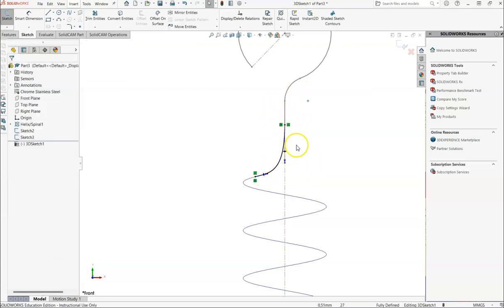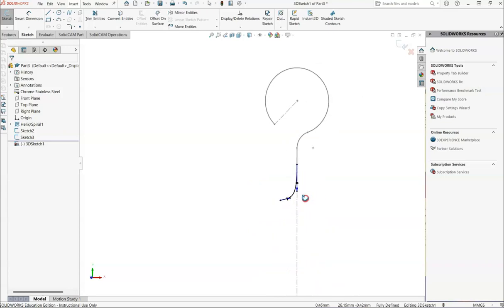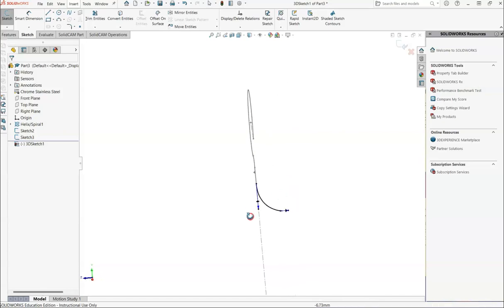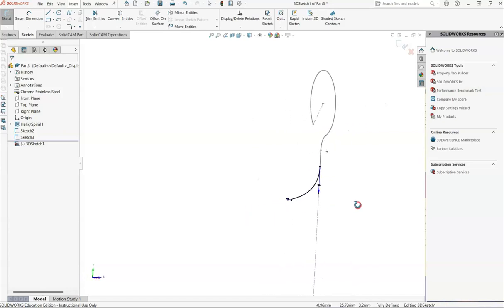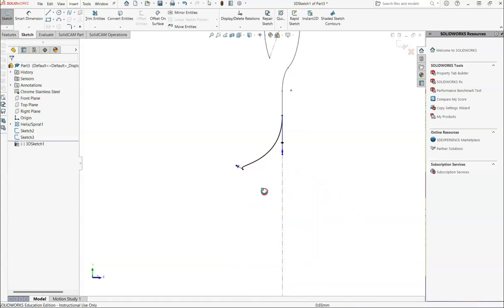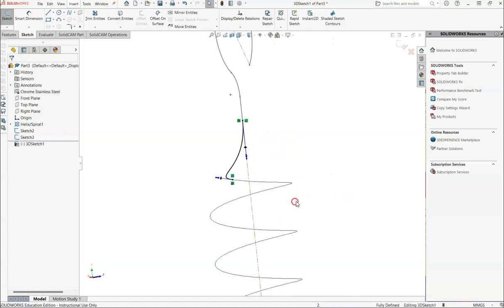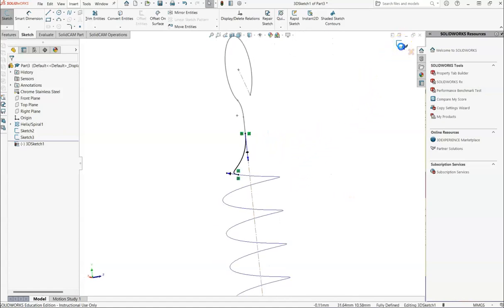It's going to kind of bend and reshape itself so that it is tangent to those 2 different lines, even though it technically is breaking the planes. And if you rotate around, you can kind of see it is breaking the planes in a different way. When I say breaking the planes, I mean it's not on a flat 2D surface. This is actually left and right, up and down, and forward and backwards at the same time. It's a 3D sketch. And I'm going to hit sketch.